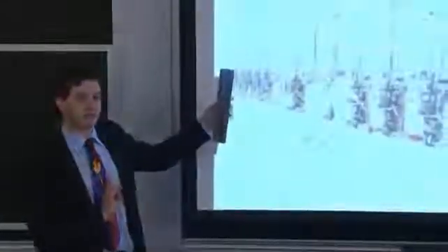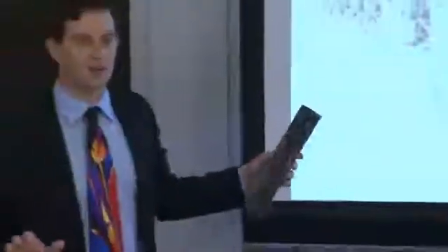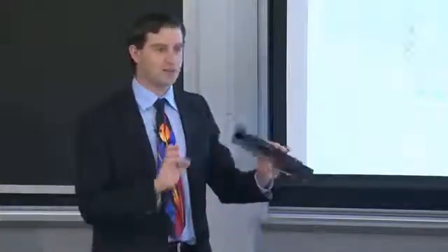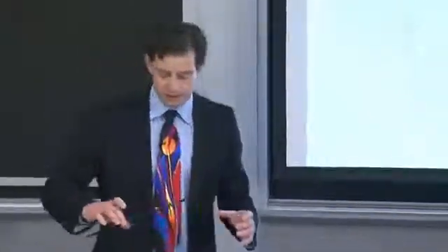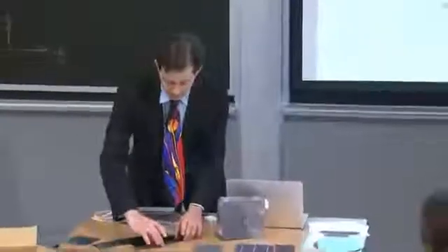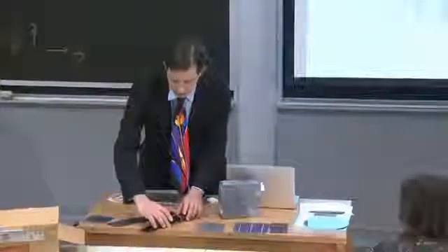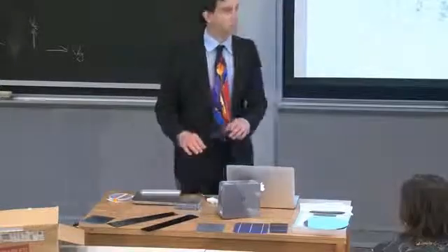The growth method to make this, though, was extremely intricate and involved, among other things, control of the temperature of the liquid silicon to within 1/100 of a degree Celsius at melting temperature, which is an extreme feat of engineering. The uptime of these pieces of equipment, meaning the growth time, was around 50%. And the other 50% of the time, the operators were trying to make it work. So it grew very, very thin material, wasn't able to scale to the form factors that we see nowadays. The throughput was quite low, the cost was high, and so it didn't quite make it. But from an engineering point of view, it was a marvel in terms of what they were able to accomplish.